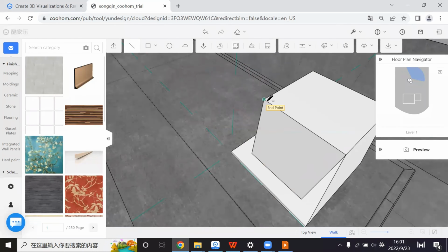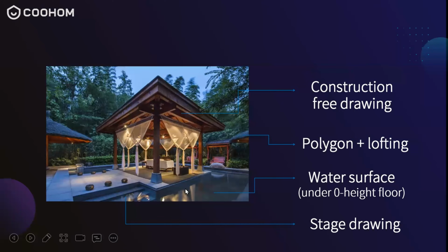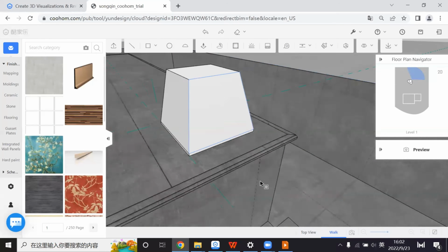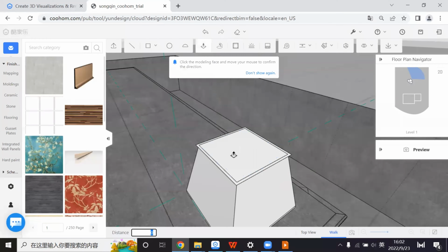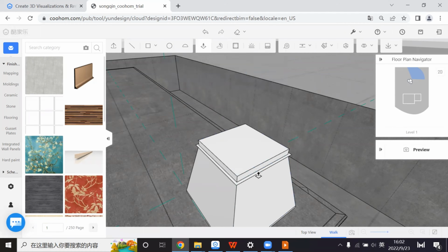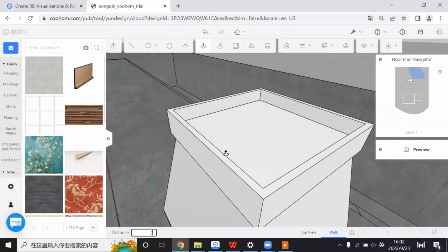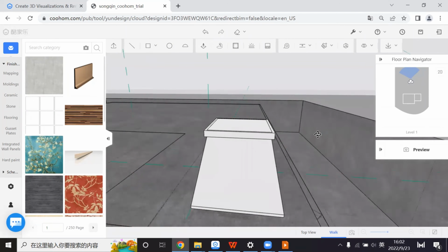This one, the same. Yeah, you can continue to draw like that. But also here you can see the border. So continue using the offset. See? And now push and pull. Push up the same, for example, 20. And also here, up 20. Now you can have the border.